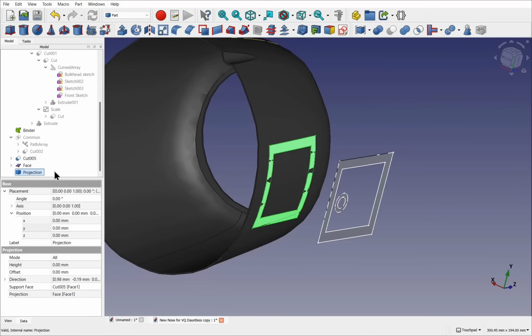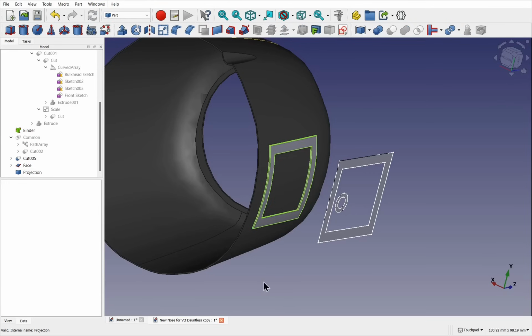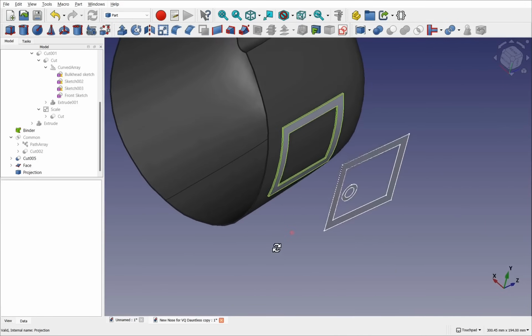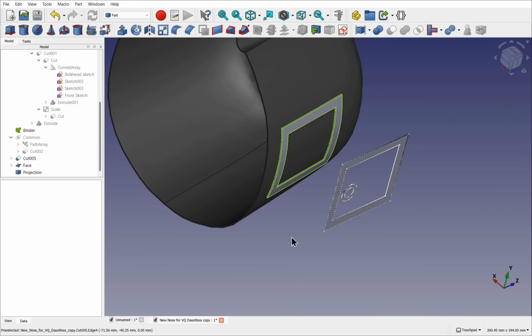That's on that surface, which I can create some height with. I can set this to say 5. And that extrudes that out from that surface. Let's set it to 1. And now we've got that feature upon there. I can union that back in to the object.